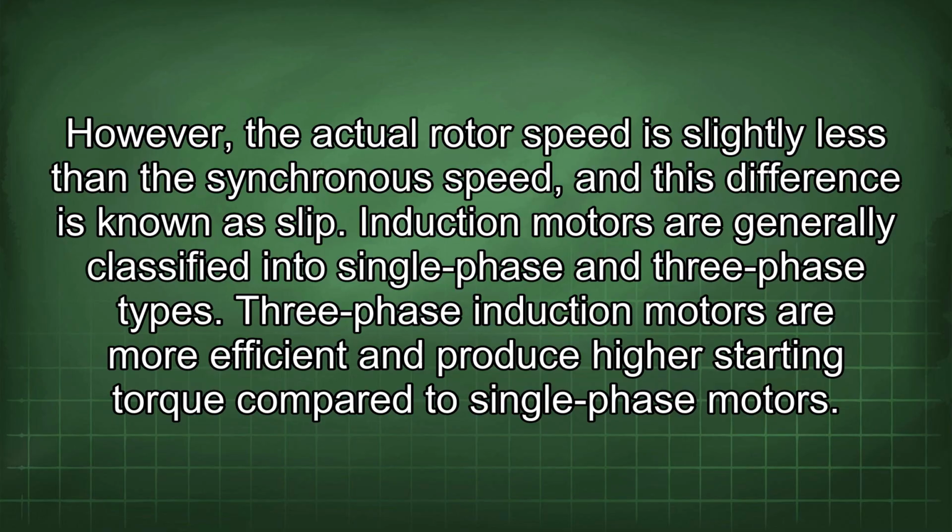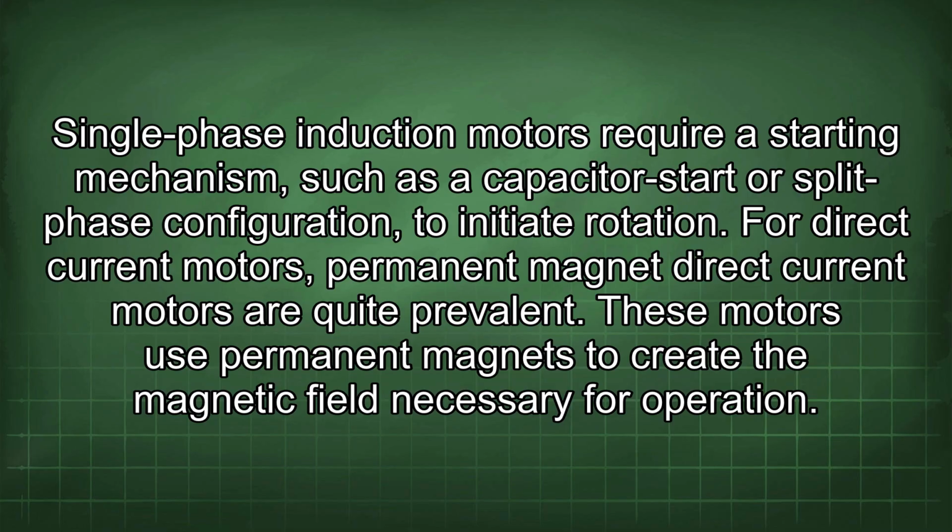Induction motors are generally classified into single-phase and three-phase types. Three-phase induction motors are more efficient and produce higher starting torque compared to single-phase motors. Single-phase induction motors require a starting mechanism, such as a capacitor start or split-phase configuration, to initiate rotation.